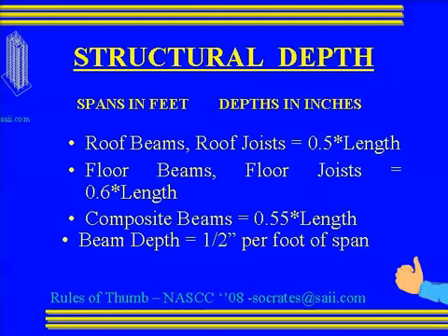But I tell you, I just simply remember a half inch per foot is a good place to start, even though we can be a little bit higher. So you do that and you add a little bit, you're okay. And it depends how much you want to give to the rest of the design team in that first meeting. You do this calculation in your head and you find out it needs to be 16 inches, but you may say, I need a 21-inch beam right here. So that you can give it to them later and they feel good. Because then they forgot that that 16-inch beam needs fireproofing on it and there's all these other things.